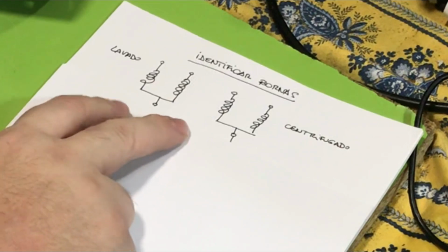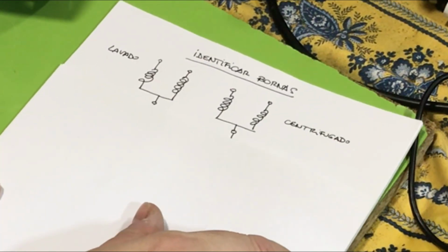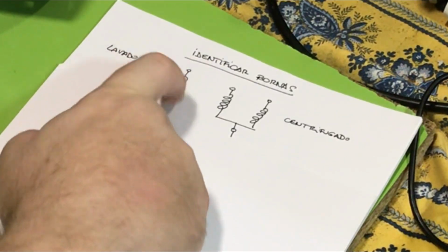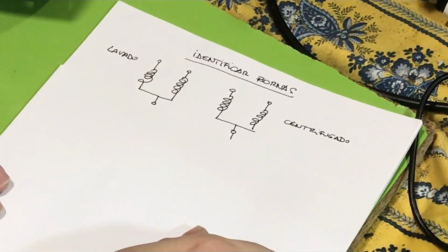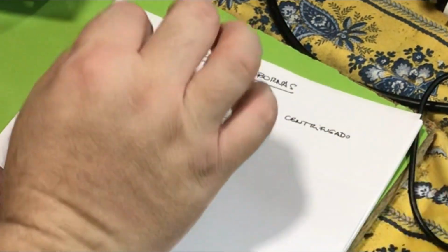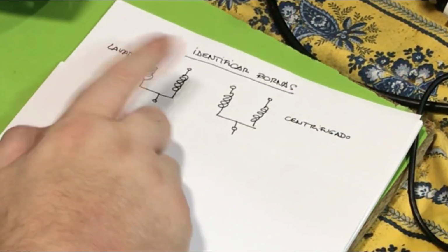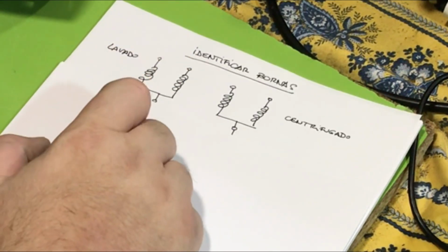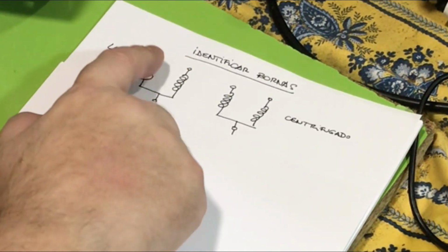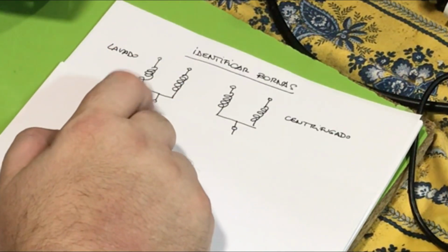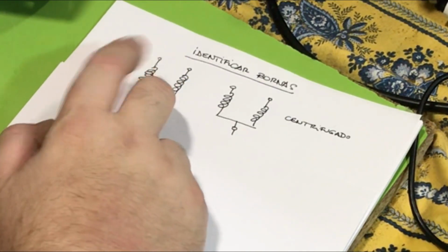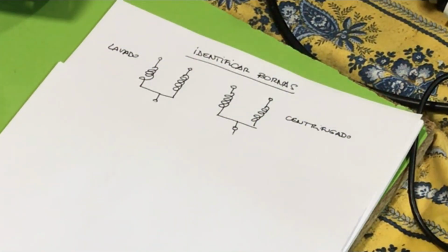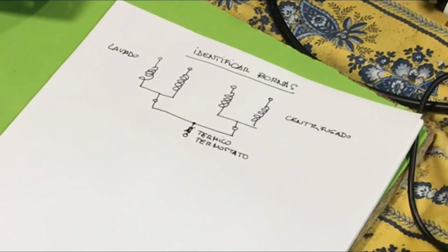It is easier to find the connections because just with continuity, with a tester, or maybe with just a little spark, it is easy to know which group of 3 terminals correspond together, and when we have separated the 3 and 3 terminals, it's easy to test.